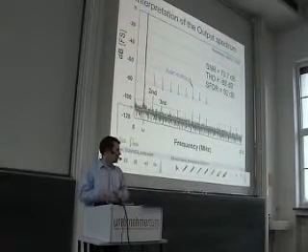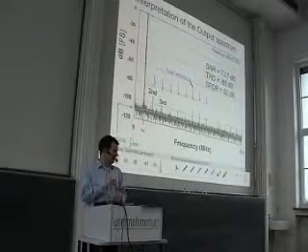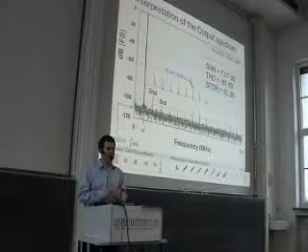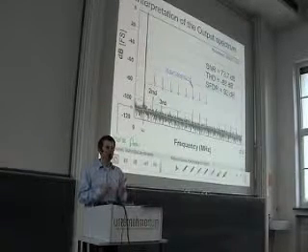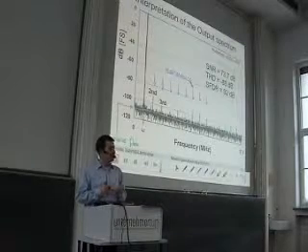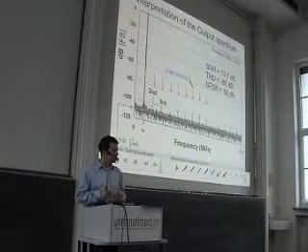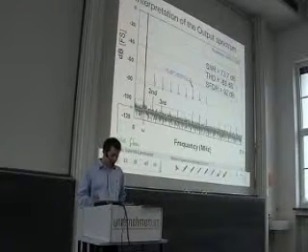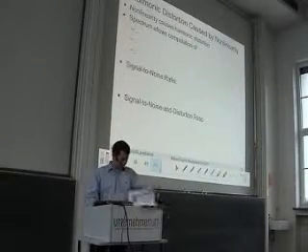So the good thing with this measurement is we see the noise and we see all the non-linearity in terms of harmonics. We see the signal that is coming out. And therewith we have everything that we need to compute a signal to noise ratio. So let me summarize this here.